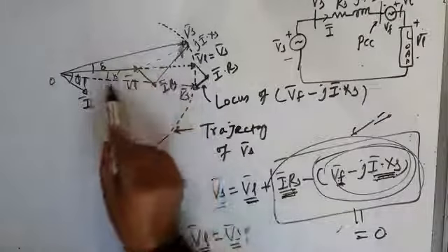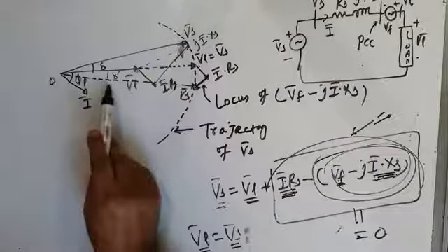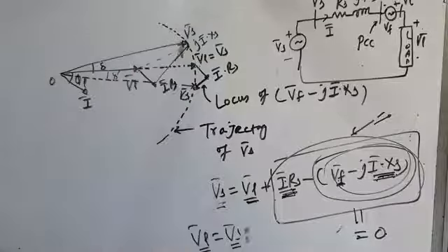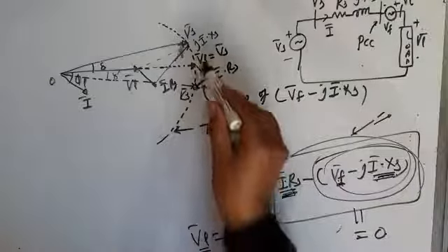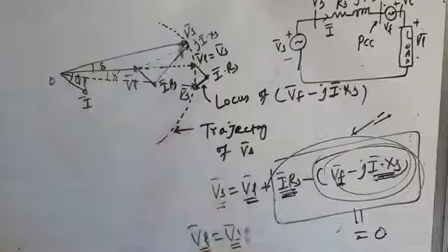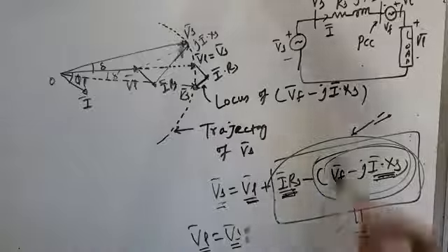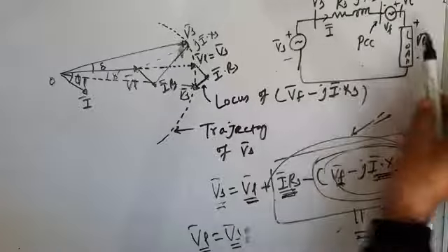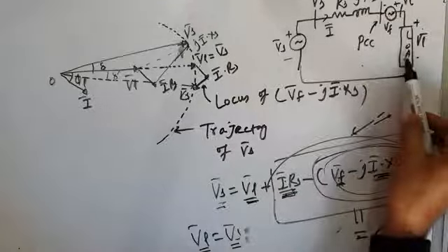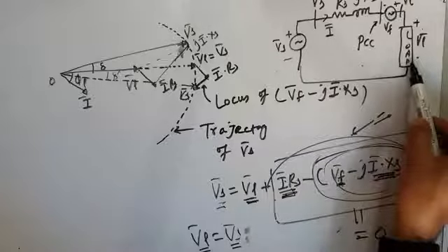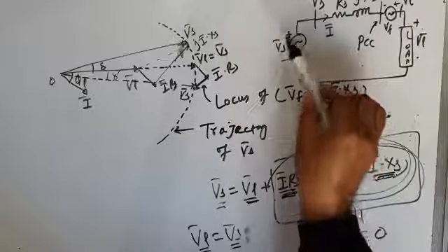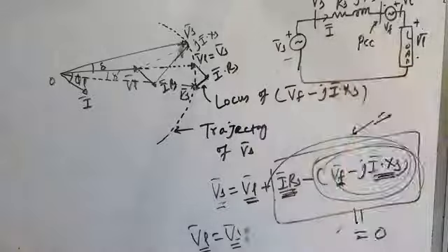Actually, even if you get a phasor diagram like this, which shows that your source voltage lags the load voltage by delta dash or by delta, so that VL is equal to VS, load voltage is the same as source voltage, so that load voltage regulation is done, it does not mean power flows from load to source. Power can never flow from load to source, because your load is a passive element and source is an active element, and power always flows from active element to passive element. I will explain that a little later.